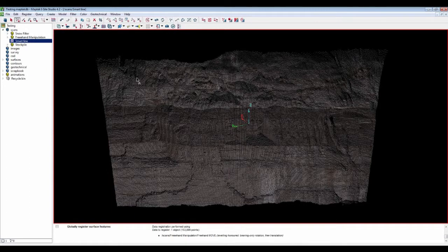And basically, a Smartline, just like creating a line, you're just digitizing a line along points as you click. But Smartline was actually really good at generating a line along a toe or a crest or the edge of a building. So anywhere along an object where there was a large angular change, it was really good at defining that edge for you. But we've done some changes to it to give it a little bit more capability.